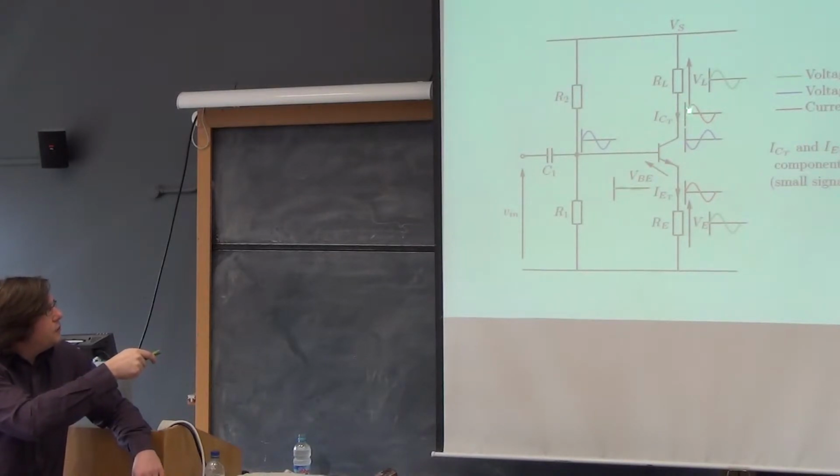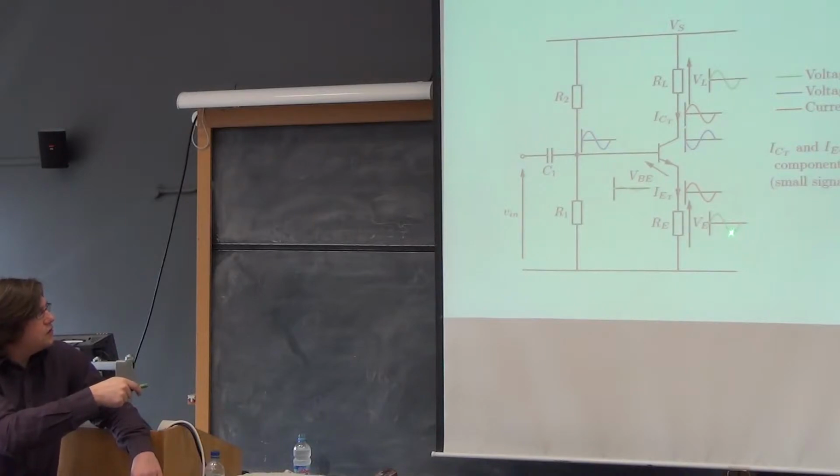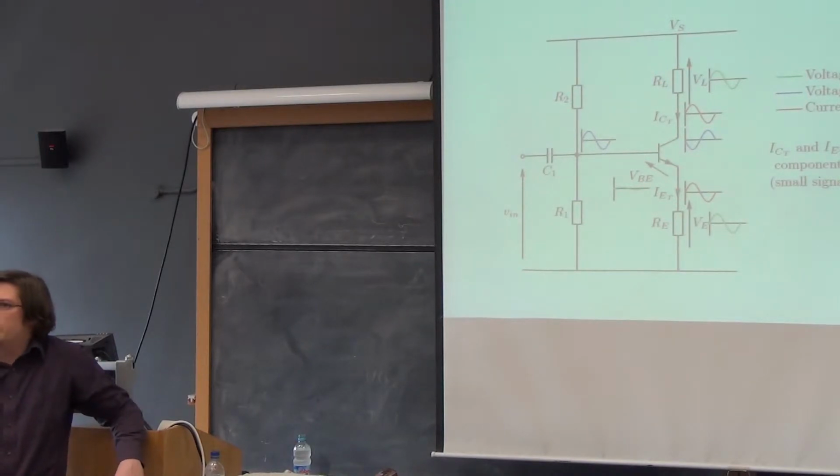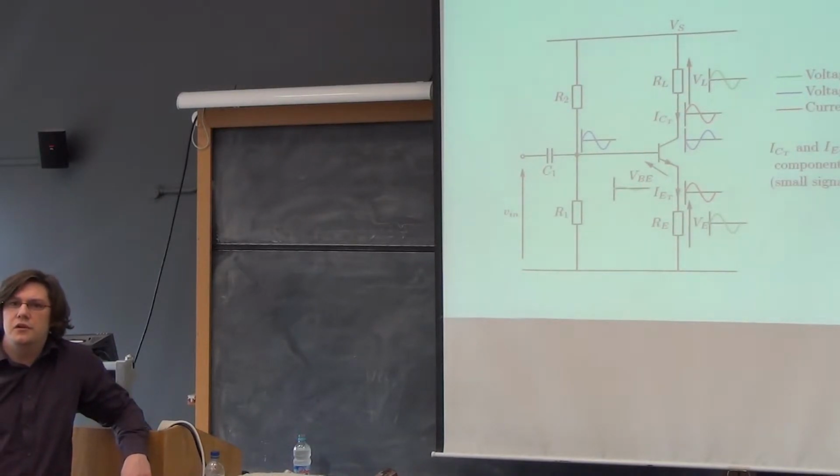And this current flows through the transistor's collector and into the emitter and then out again and through RE, causing this green voltage to appear across RE. And this voltage subtracts from this one to leave only a very small amount actually across VBE. So the effect of not decoupling RE is that the voltage across RE subtracts from the voltage at the base to leave only a little bit for VBE. And that is what reduces the gain of the transistor. Or rather, the gain of the transistor doesn't change, it's just the apparent size of the input signal has been reduced.